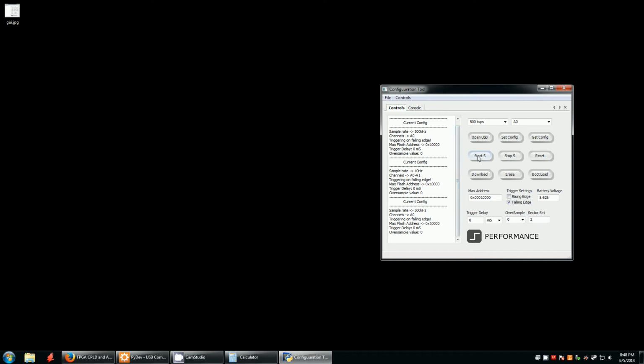So we'll kick off the recording engine with the start command, start recording. Now download data, and you see our data is downloading 100 blocks at a time, and so that's 6,200 data bytes at a time, and it only takes a couple seconds to download. Then we'll use a plotting tool, check out the plot. This is a 1 kilohertz square wave, and so it's about 0 to 3.1, 3.15 volts. Just to look at the oscilloscope.